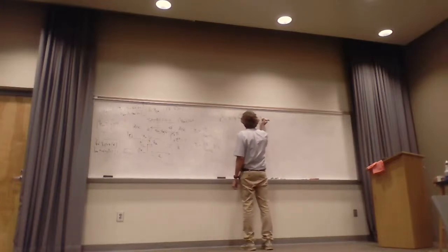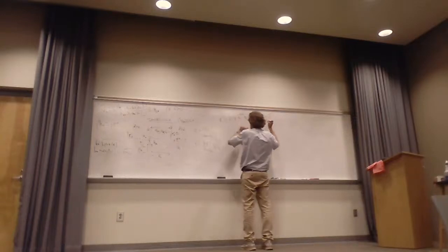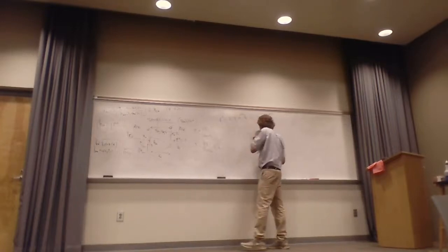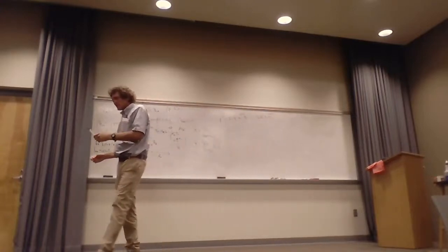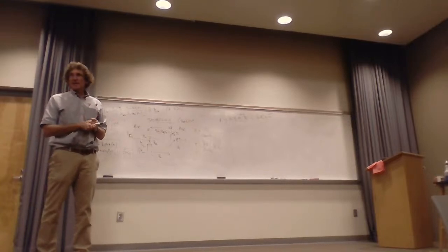And it makes this equation look like 2 E naught incident times the transmission coefficient, tau 1, times e to the minus alpha, and then z here would be the thickness of the shield, L. Here, I can just put L. That, in fact, would be the electric field that leaves the shield. Are you with me, class? Now, there's one last thing.